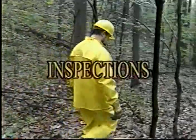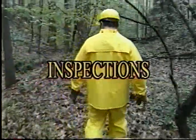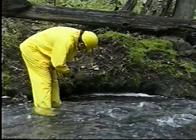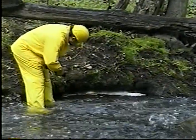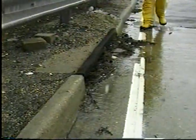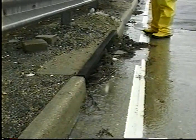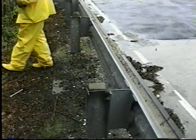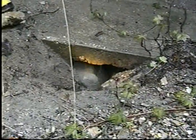Drainage inspections should be made quarterly and during and after each major storm to evaluate the need for cleanup and repair. The best time to look at drainage facilities is during a storm. The inspector should be alerted to any pavement cracks or settlements that appear after a severe storm, even if these defects are small, as they may be evidence of a larger problem.